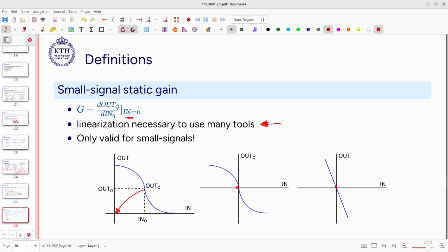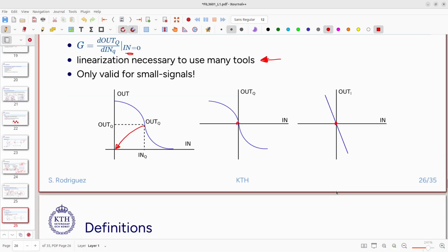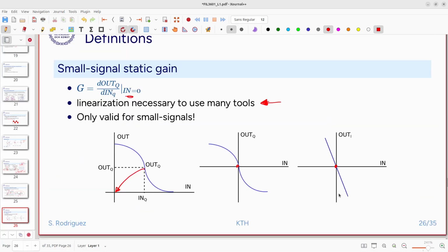In the next lecture we will do this for a transistor. For now it is just important that you understand that this step is necessary, and that every conclusion we have in a simulation that is based on a small signal is only valid for very small excursions from the operating point. So nonlinearities are not assumed here because we have linearized the circuit. We will have to handle nonlinearity with different kinds of simulation techniques.